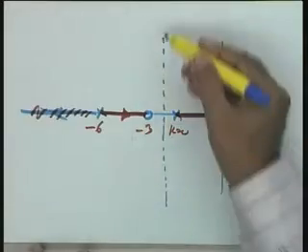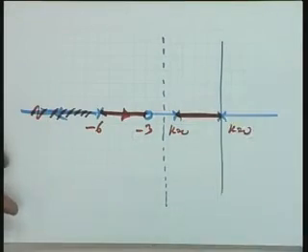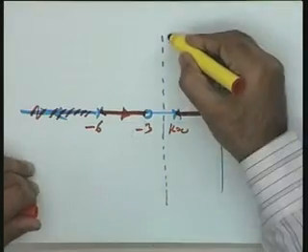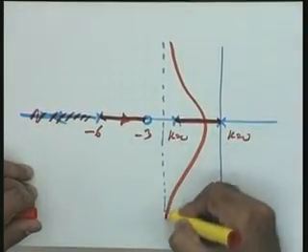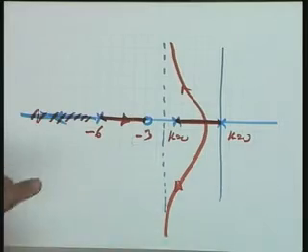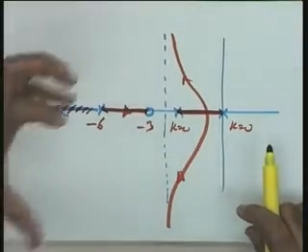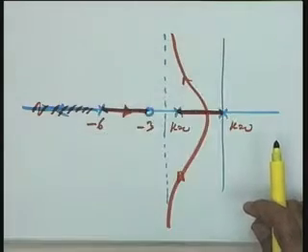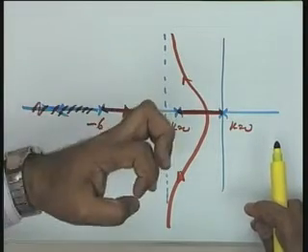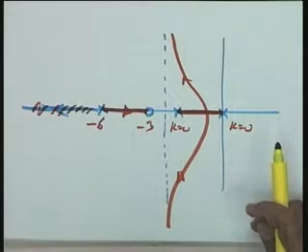And now I have drawn the asymptotes, which turn out to be like this, and therefore you find that the root locus plot becomes like this. You find the effect, it is a tremendous effect on the root locus plot. The total plot has been pulled to the left, and pulling the plot to the left means stabilizing the system in general for all values of k.